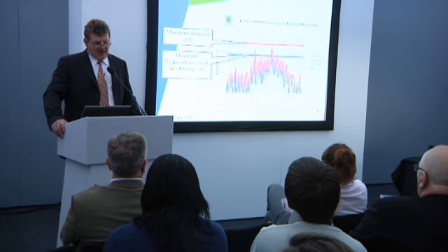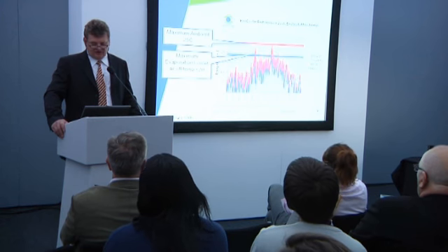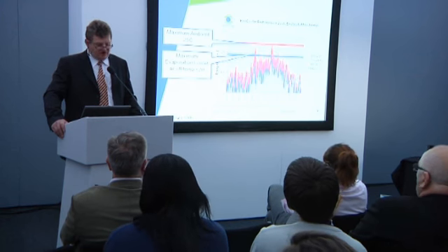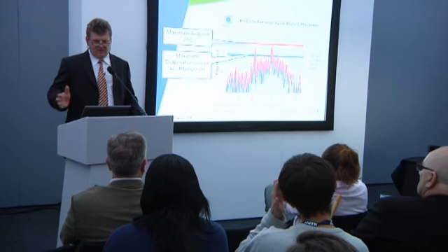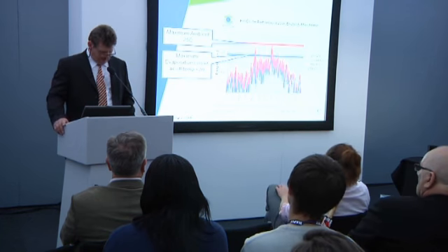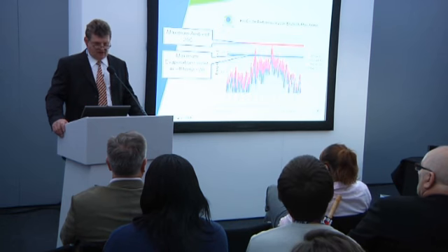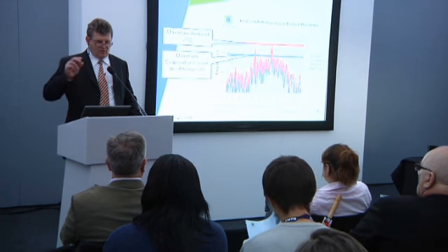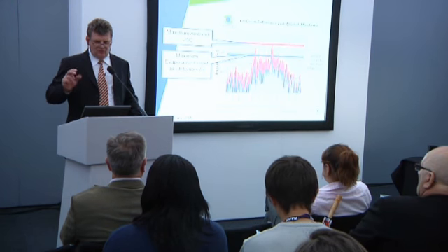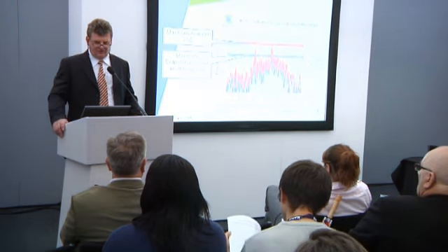However, passing the air over one of those wetted filter pads means that the air temperature would never normally go above 20 degrees centigrade. So that simple wetted filter pad in an evaporative cooler will give us an unlimited amount of air below 20 degrees centigrade without any need whatsoever for refrigeration.